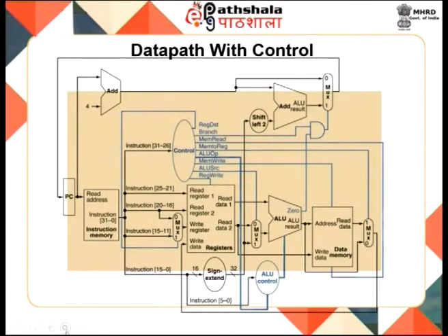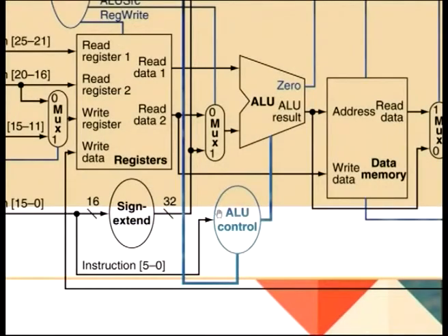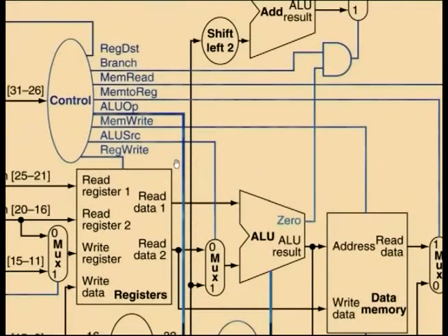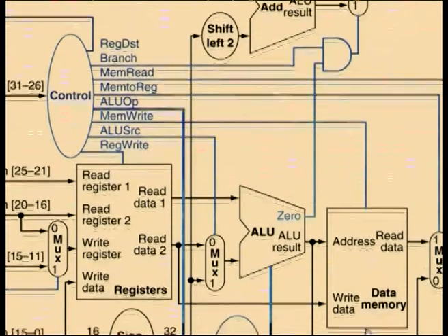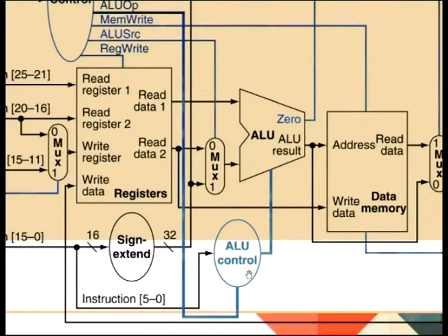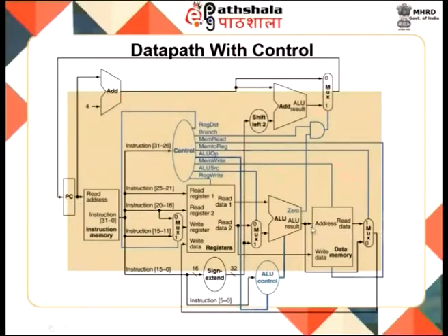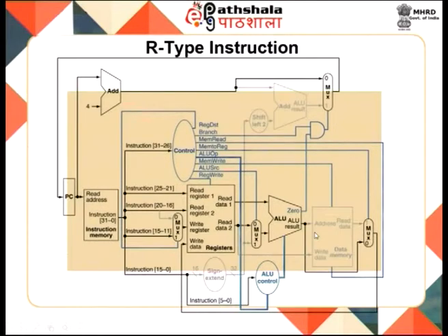Apart from that, you also have an ALU control signal unit here, a smaller control unit, where it takes the 2 bits from your opcode part. So, you have your ALU op 2 bits that are given to your ALU control unit, which in turn, along with the function part, as indicated in the table in an earlier slide, will decide what ALU operation is to be performed by the ALU unit. So, these are the various control signals.